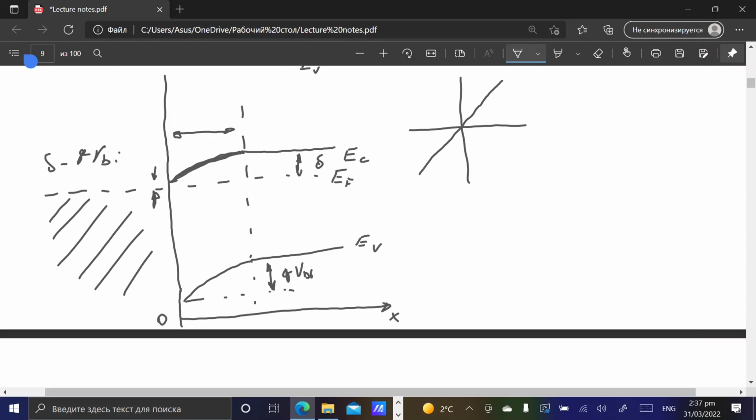It doesn't mean that a rectifying JV curve doesn't look nice. It just depends on what you want. But ohmic contacts you will deal with in any case. In any semiconductor device you will have an ohmic contact, because you need to inject or extract charge carriers somehow. So that is an indispensable part of any device.